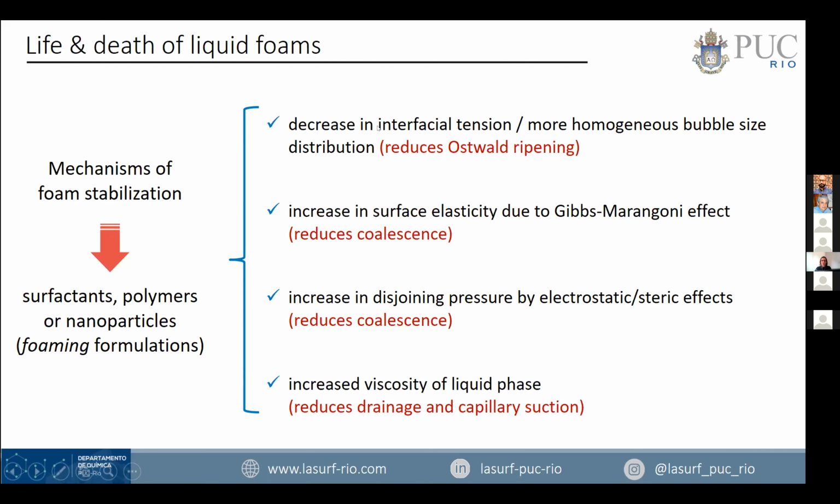And then while this first effect here is more important for the bulk foam, the increased viscosity of the liquid phase is more important for the liquid foam. Then you have a decrease in interfacial tension and also in surface elasticity and disjoining pressure, affecting the foams in porous media as well as in the bulk phase.